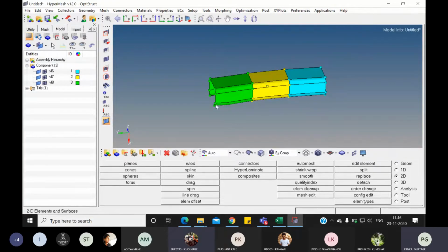Okay, okay. Previously, that file was like this. Let us consider it was prepared in CATIA. Then it is in IGS format, right? Then it is imported, and meshing is carried out on that particular file, and then it is exported by export model. If you export the model, it would be saved in the meshing format, meaning .hm. So those are exported part-wise and then connected to each other. That's why it is showing that.